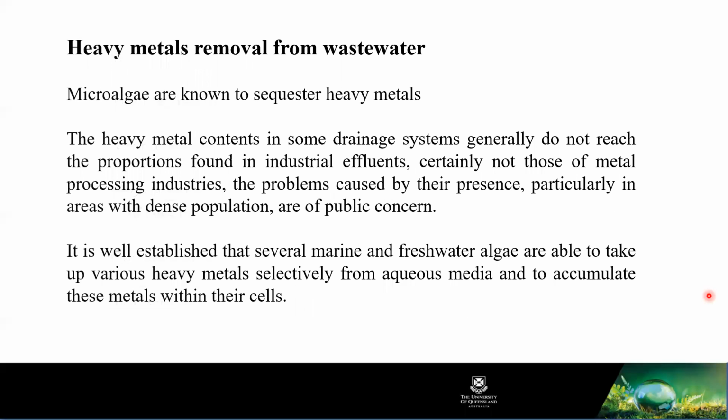Heavy metal removal from wastewater, as I told you: iron, we are able to significantly remove, and also lead, we are able to remove significantly to below the detection limit. We have some proven algae out of the 100 algae in our current culture collection. That's the major advantage. That's only possible with a microalgae-related treatment. In other processes, it's pretty hard to remove heavy metals, but here it's possible.